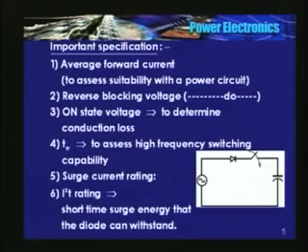At omega t is equal to pi by 2, input voltage is at the positive peak. Capacitor voltage is 0 and it cannot change instantaneously. So what happens when I close the switch? There is going to be a large inrush current.